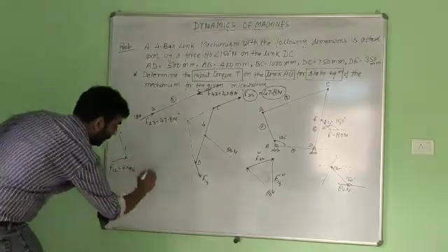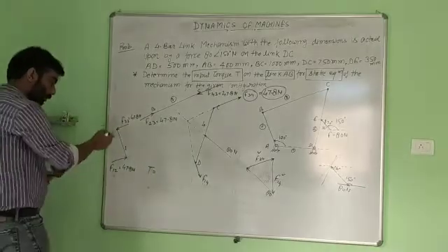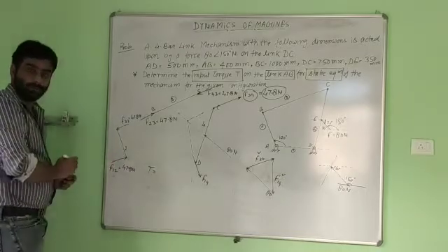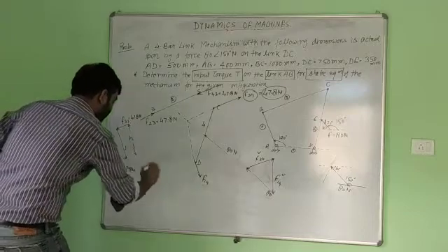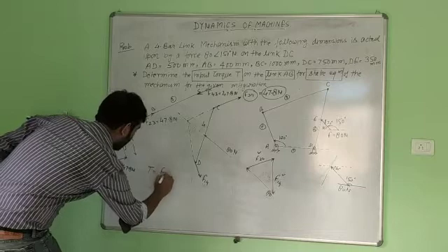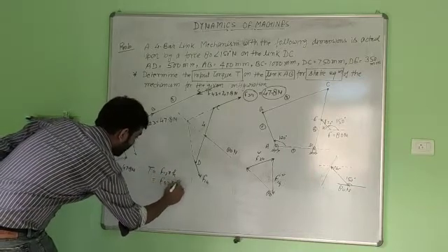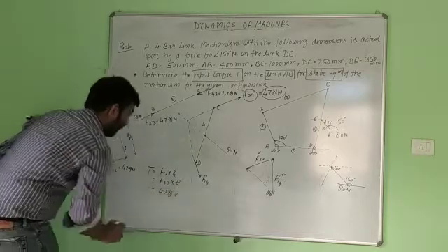So we will apply a torque equal and opposite to the moment. Let's say this distance is h. The moment will be F12 multiplied by h, or F32 multiplied by h, or 47.8 multiplied by h.